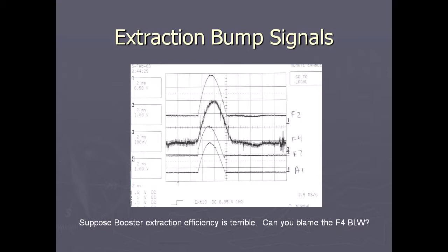More importantly, if I pull up these pictures, I have no idea intrinsically what they should look like. How do you know what they should look like? Look at them when they're healthy. Look at a reference. The important thing is that the reference picture looks like the current scope picture, so you adjust the scope. Hopefully whoever took the reference picture had all the same voltages, I would hope. But if they didn't, make sure that your scope looks like the reference picture setup, and then you can compare things.